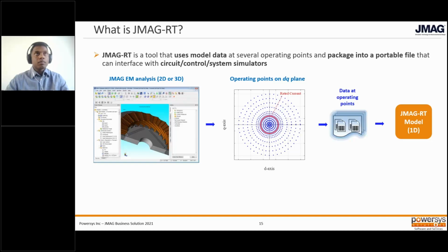Excellent. And then there was a clarification, I think, about the iron losses in the machine. So you're taking an FFT of the approximate PWM waveform, and then from there calculating what the losses will be. Mm-hmm. That's correct.